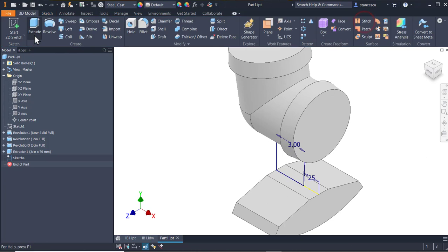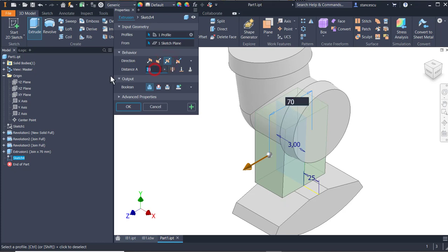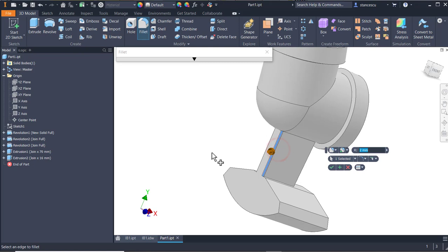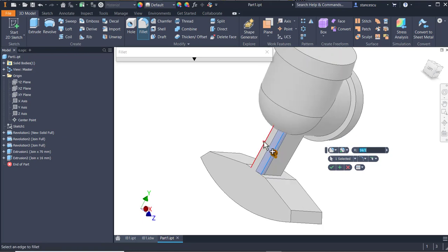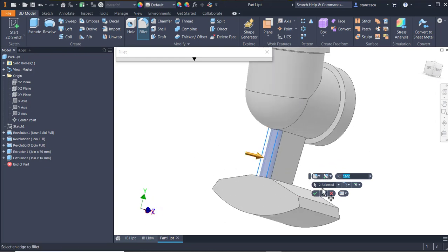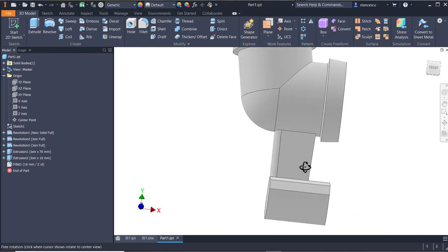16. Extrude, symmetrical on 16. Okay, then let's round with the radius 8, not 8 but 16 divided by 2. We use exactly the dimensions in the drawing. Okay, now we can add some fillets.